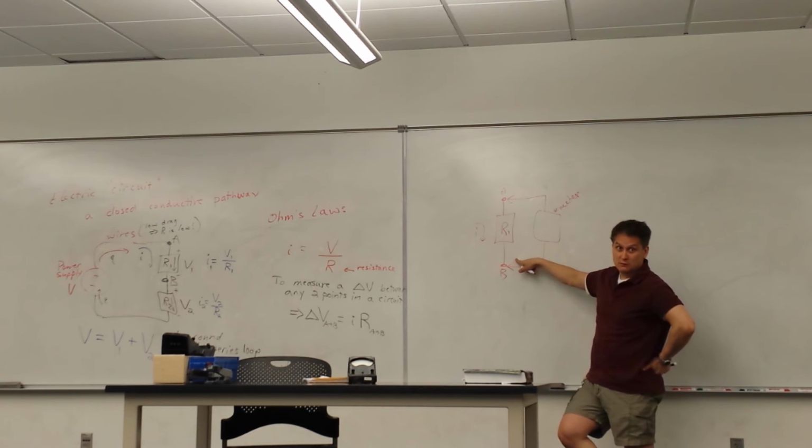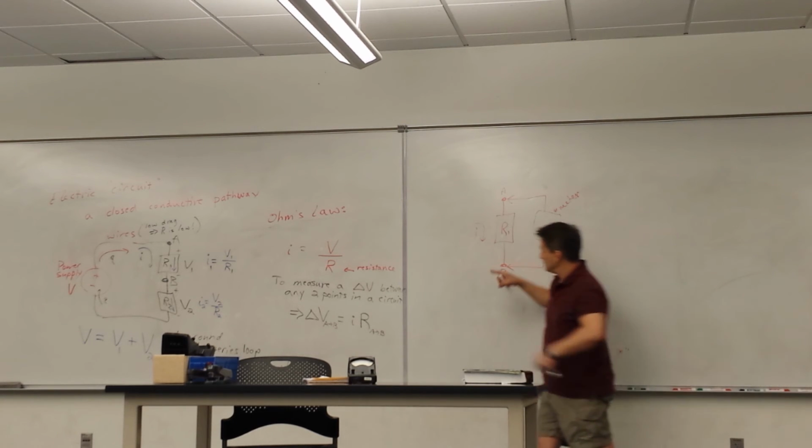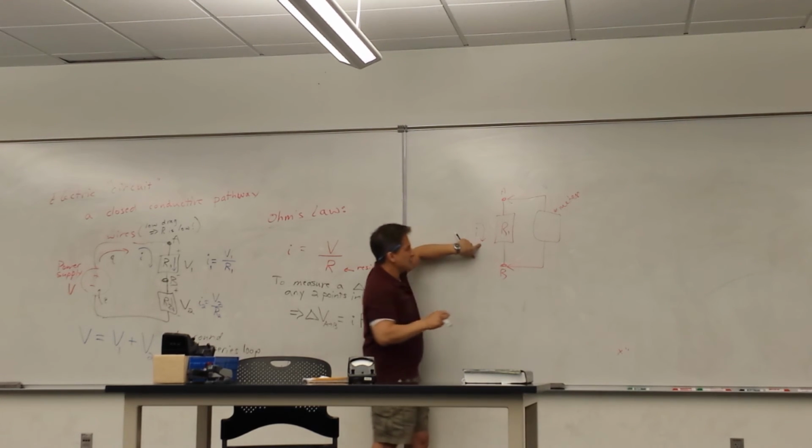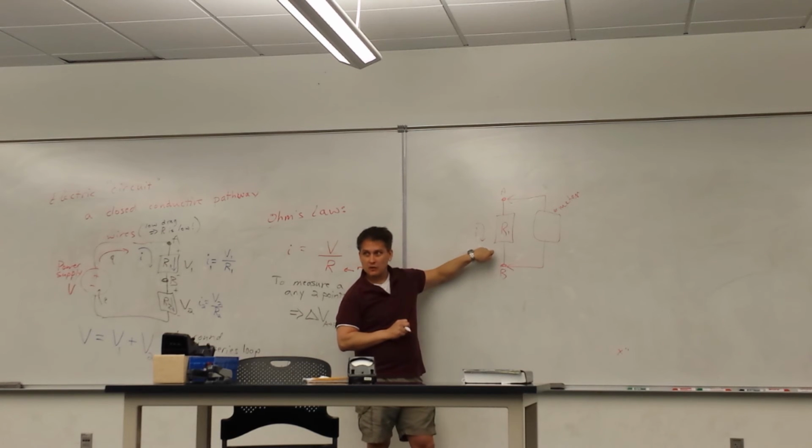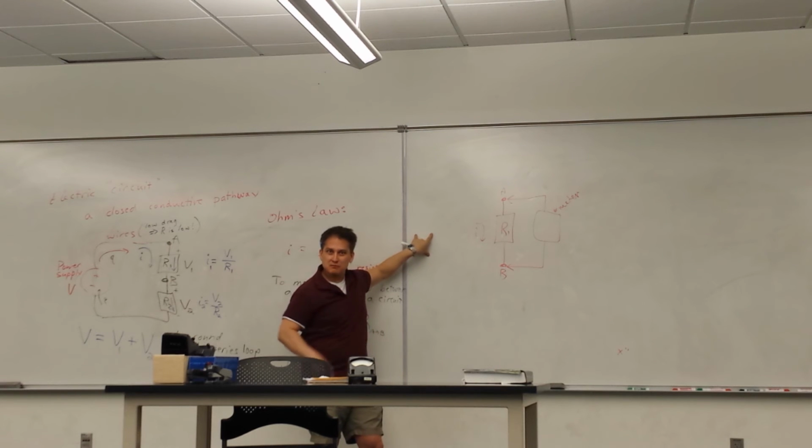Well, there are potential problems. How much current flows across this region, and I've got current flowing across this region, I may inadvertently saturate my power supply's ability to produce electric current. If I do that, I'll disturb the current, and I'll disturb the circuit to the point that whatever it is I would be otherwise measuring, it would be of particularly no use.